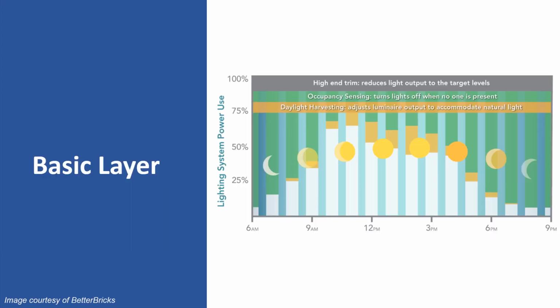The basic luminaire level lighting control layer places key elements of an autonomous yet groupable control system within each luminaire with a versatile range of inputs and outputs. Inputs include the occupancy sensor, light sensor, manual controls, and any programming. The control functionality decides whether and how to change the lighting based on the configured sequence of operations. Depending on the specific system, variables can include scheduling, switching, dimming, color tuning, and data. These combinations of inputs and outputs enact a range of popular control strategies, including occupancy sensing, daylight responsive control, scheduling, high-end trim, manual override, and more.